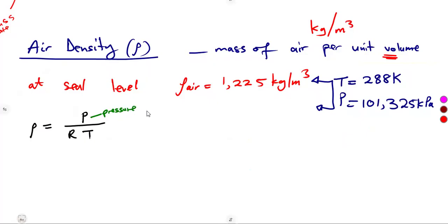If you are using pascals, it affects the value of R there. If you are using kilopascal, again, it affects our R. Our R will be taken now in kilojoules. So our R for air is 0.287 kilojoules per kilogram Kelvin. So you must be careful.